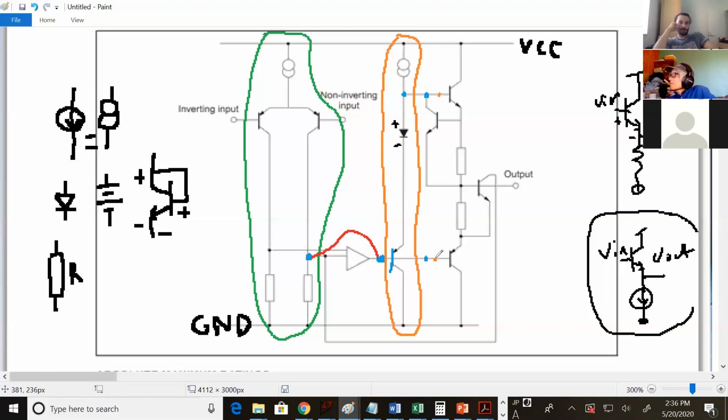2 VBE on. Does this give you 2 VBE on between those 2 bases? In other words, does this have crossover distortion or does it not? It does, right? Because of the resistor? You can ignore these, they're just for protection. Then I would think it wouldn't have it. Well, let's see.